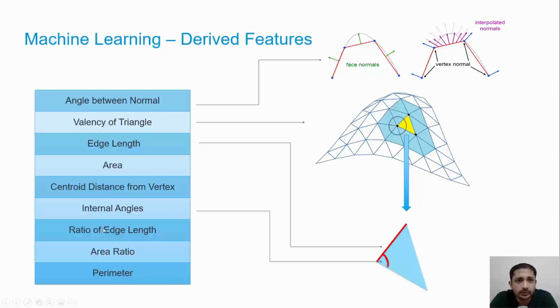So for this, we are more focusing on properties like the angle between normals of two adjacent triangles. A curved surface will have an angle more than 0. A planar surface will have two adjacent triangles with 0 angle between their normals, and so on. So also getting a sense of how small or how large the curvature is. Such kind of information will not change when the location and orientation of the body change, right?